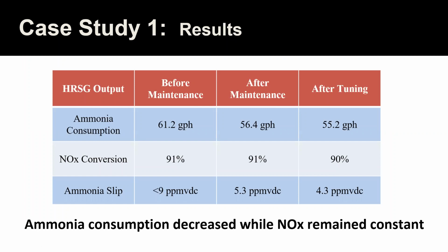If you're at 3/4 to 90% of your ammonia slip limit while starting up, or on a new installation or a retrofit, this should pump your brakes, and you should be looking into something like tuning or making sure that the proper volume of catalyst was put in there.